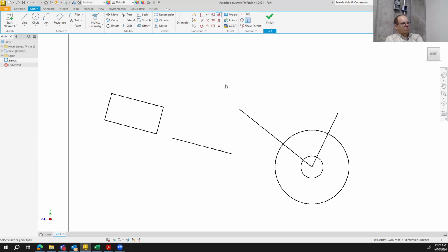This is a fun one, but also potentially an annoying one, because basically you can say, whatever we have, this is the one that rules everything. Nothing else can change anymore, right? So if we choose that line there, for instance, to be a locked one, then I would no longer be able to move this line up and down. Because, I did the double lock, that's not what I wanted. Let's just lock one of these. Okay, already put that constraint, let's get that constraint right here, right, I can always delete constraints.